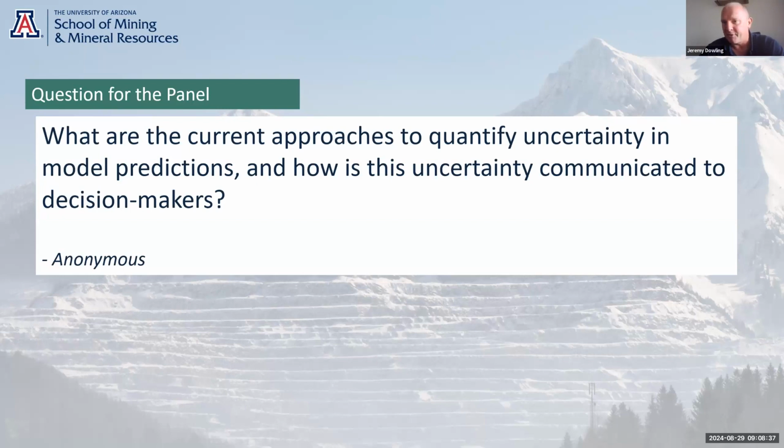So a set of predictions in the groundwater model that could be done to support a pit slope design might assume there's 4 dewatering wells and numerous horizontal drains included in the slope implementation to create depressurization that is needed for geotechnical stability. So that's the assumption in the predictive model for the design.